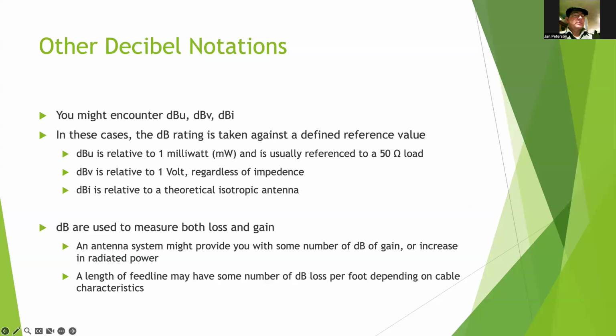In the direction it's pointing, it will actually give you more power than what your antenna is being exposed to. It'll concentrate that. When you're sending with a Yagi type antenna, you'll get a stronger signal than what you're putting into it. There's a certain amount of gain that comes with that antenna.